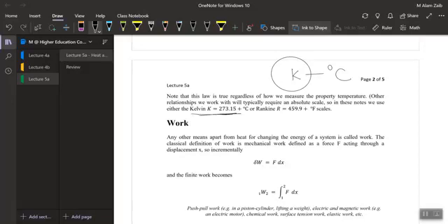If you're looking for the English unit, which defines the temperature in terms of degree Fahrenheit, the absolute temperature scale for degree Fahrenheit is degree Rankine. So if you add 459.67 to degree Fahrenheit, you will get the absolute temperature, which is called degree Rankine. So we have two temperature scales, degree centigrade and degree Fahrenheit. The absolute temperature scale of degree centigrade is degree Kelvin, or Kelvin simply, and the absolute temperature scale of degree Fahrenheit is Rankine, or degree Rankine.